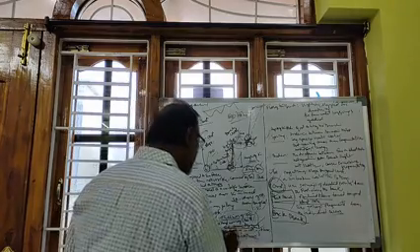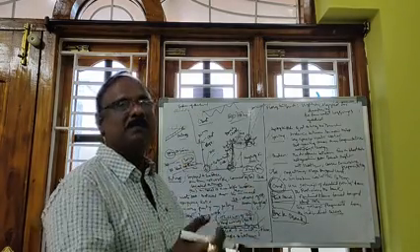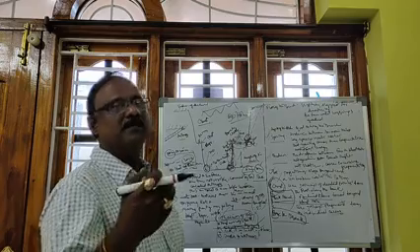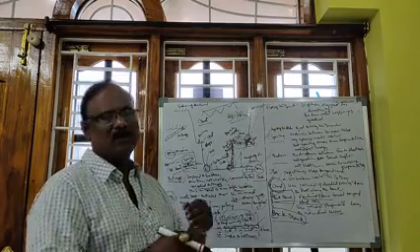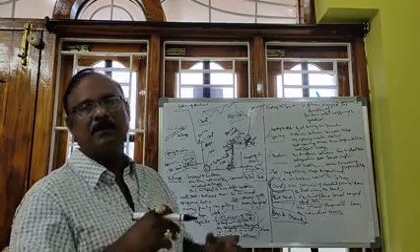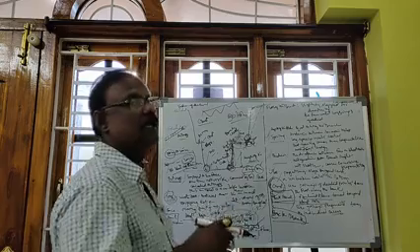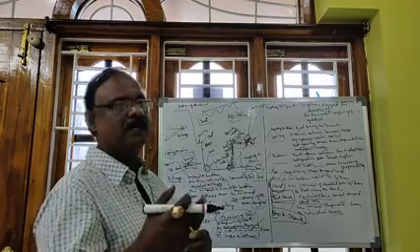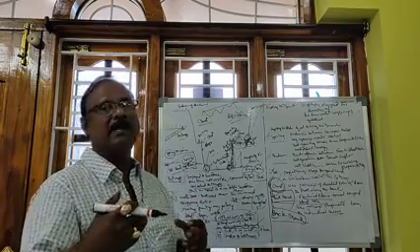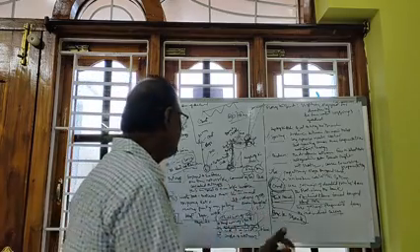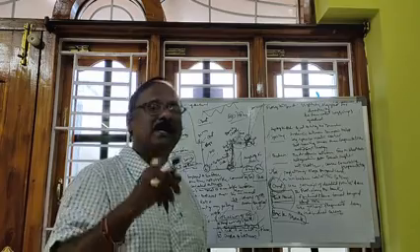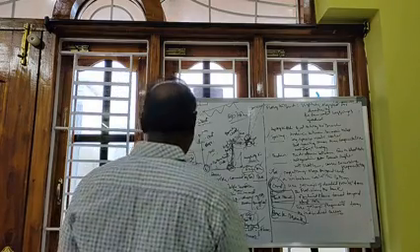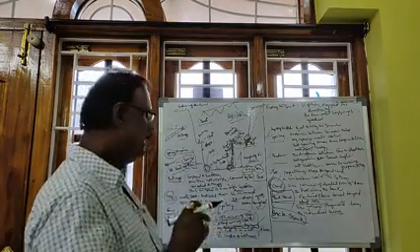So if it is a water bearing strata, the height of the bench must be much lower, around 5 meters. Five meters is viable, and not less than 5 meters, because mining is not at all possible with less than 5 meters. It cannot be more than 10 meters in a water bearing strata. Suppose the OB has the feature of water bearing strata, then the height of the bench cannot be more than 10 meters. These are the different factors on which the bench height depends.